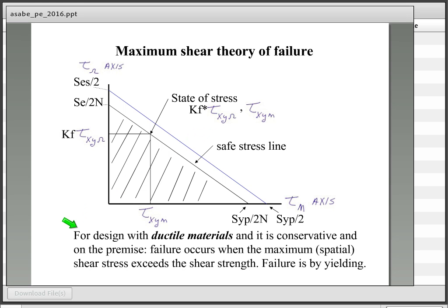And if we're dealing with shaft design, typically what we would be using is what's called the shear theory of failure, where we're dealing with the shear stress. And we'd then be dealing with the allowable endurance range in shear.